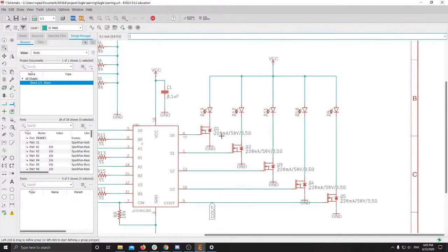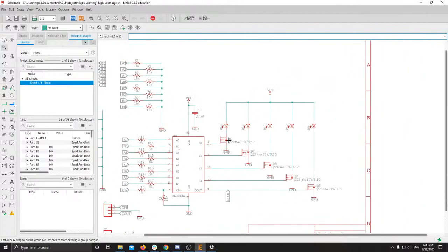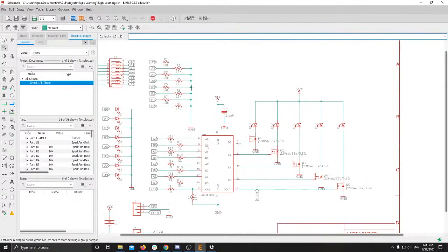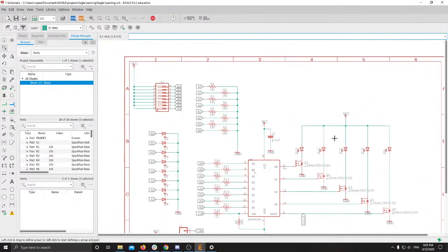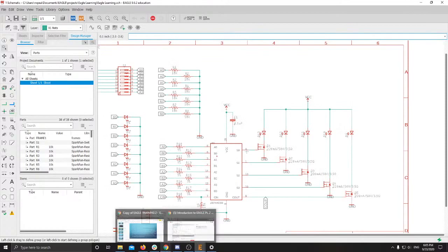So we'd want to put these somewhat close together. We don't want to have the transistor on one side of the board and the LED on the other side of the board. That would just be a bad design choice, and you'll get more of a feel for this as you do more boards, but generally, if you've done your schematic well, you can group the like subsystems together.